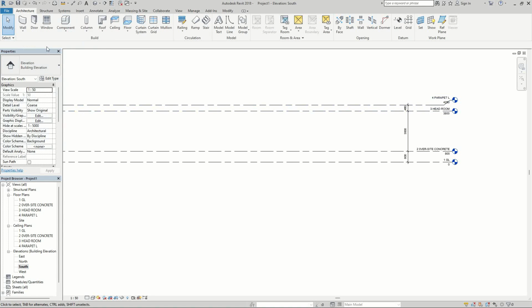Again, I also draw your attention to these two bars. These two are the dialog bar system, which carries the properties and the project browser. And as explained, they are very important. We have been working with this for the first stage to set up the drawing. It means if you have set up this position, I can easily draw on this level, wherever level I select. Now, as I'm changing this order, you're seeing the same name reference in the ceiling.